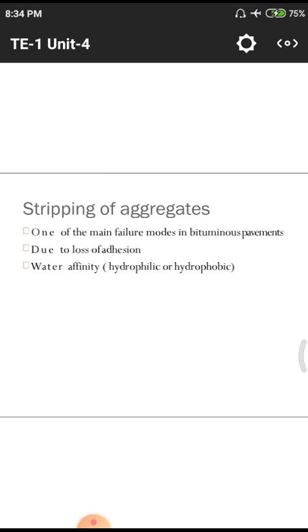On the other hand, we have to use curing. Whenever the road is constructed, after the construction we need to cure the road surface for a few days. Normally we have to cure for 28 days to obtain good compressive strength. Normal curing they follow is gunny bag curing, and in some places they directly pour some quantity of water and simply make some cement paste at the middle points.